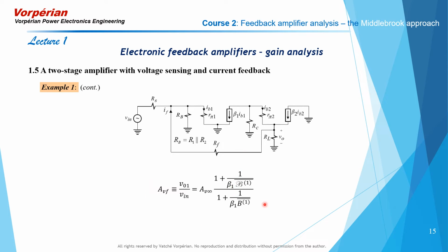That's given here. So what we have to determine now is the voltage gain with beta infinity. Then we'll determine the null inverse gain with respect to beta 1 with the output nulled, and the inverse gain with respect to beta 1 with the input set equal to 0.